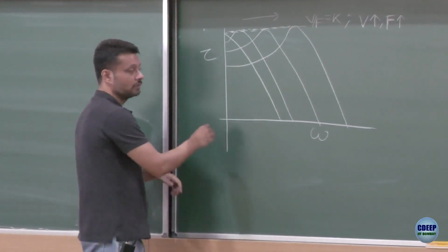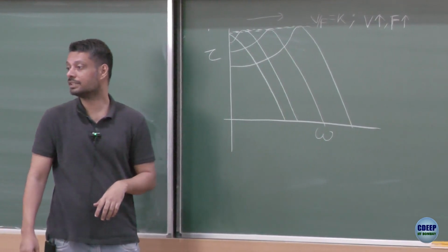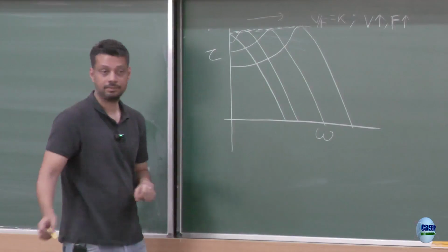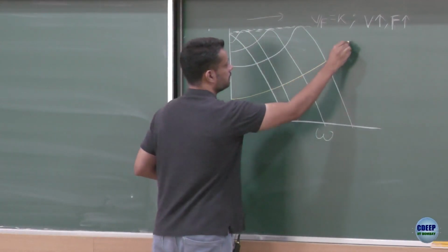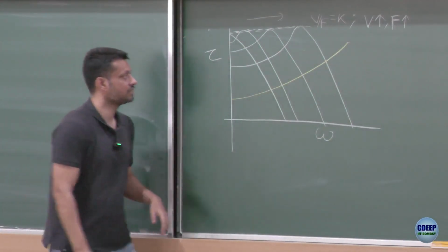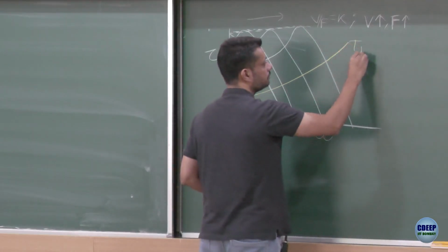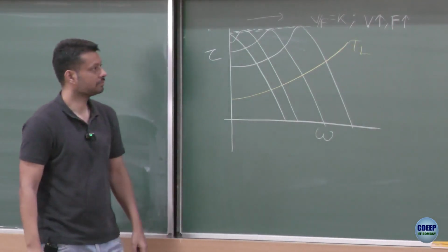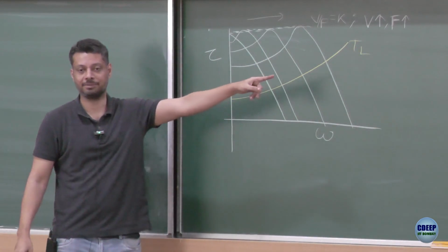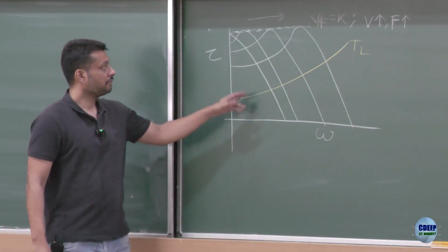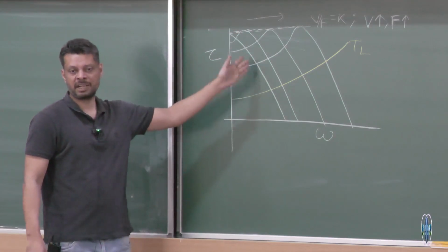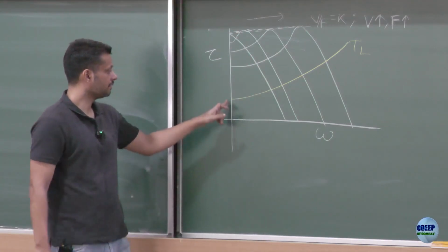You derived, right? Who said we derived? Okay, this is your load characteristics. If you have not derived, you can go and derive now. Just differentiate it, make it equal to 0, and find the maximum torque, and find the slip at which you get the maximum torque.